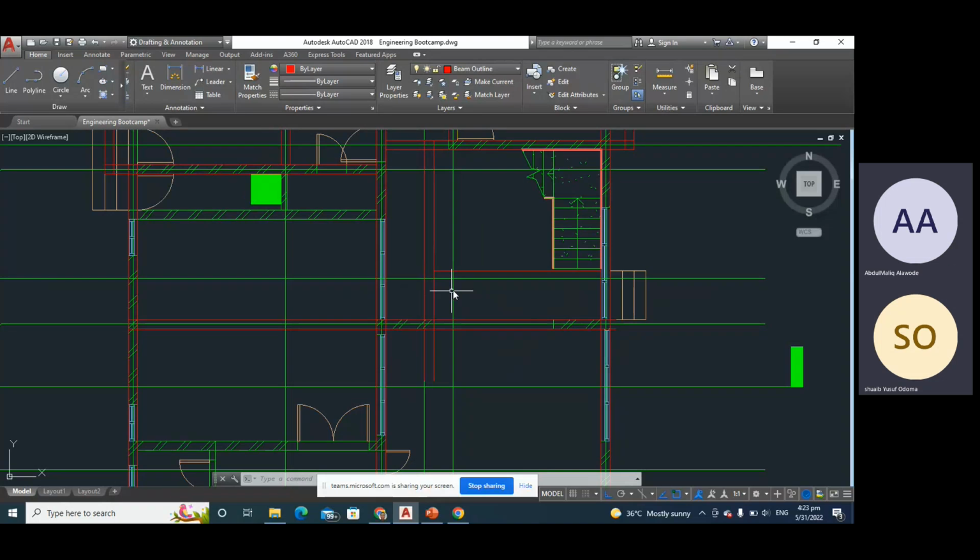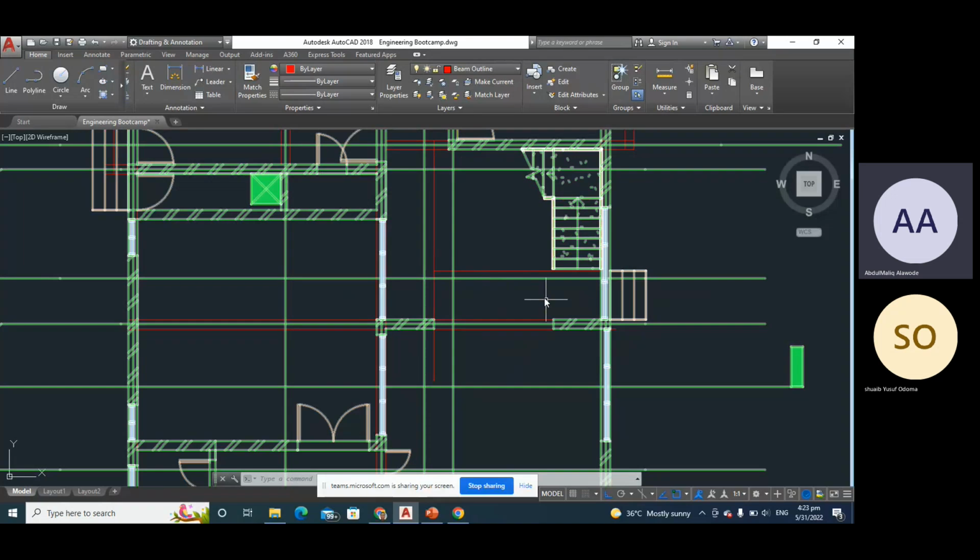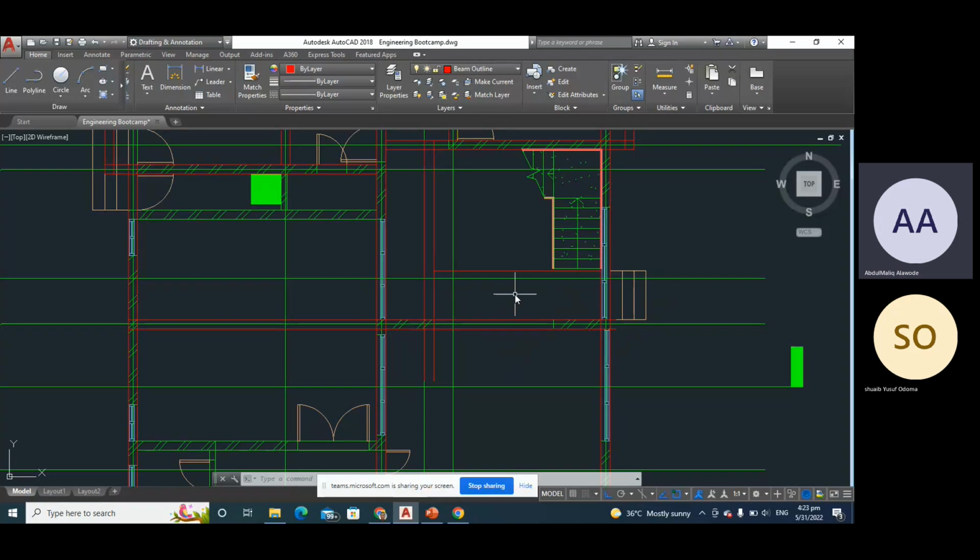I understand. So now on site, if you are the engineer and you have engineered this slab to be a simply supported slab, the reinforcement along this horizontal axis has to be placed first before they place the one on the y-axis. Do you get my point? I mean the bottom reinforcement.